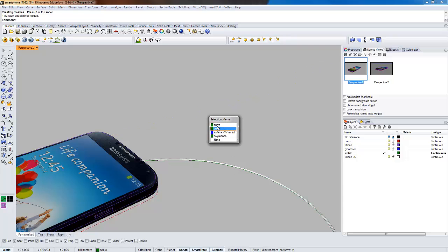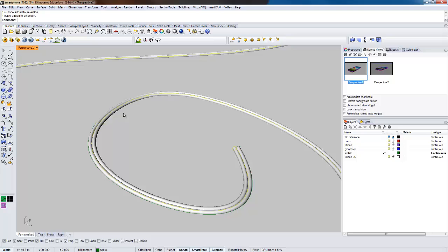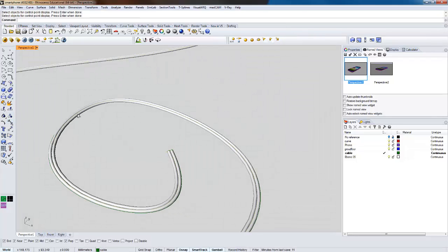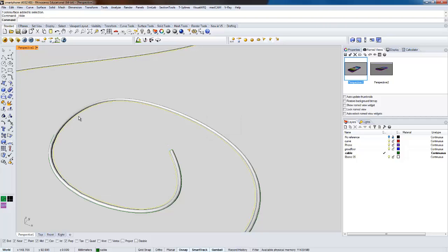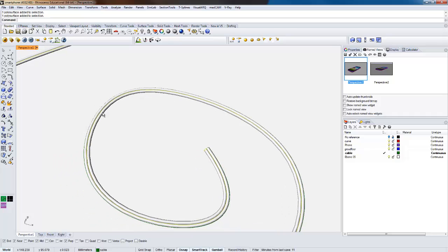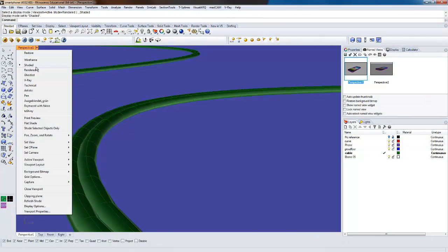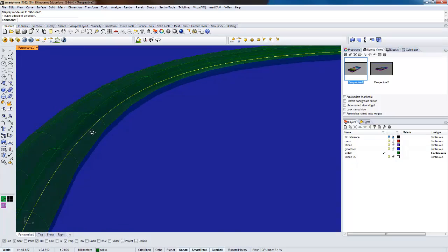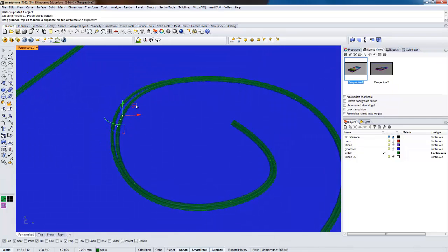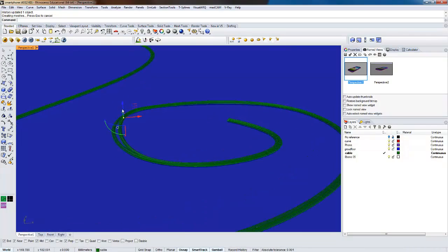And to show you what I meant before, when we change the control points of the curve, let's do it here. Points on. If you have problems getting the curve, maybe go to a ghosted viewport. You can actually see the curve better. Okay, points on. Where are they? There they are. So now you can see you can change the curve afterwards. That's pretty nice actually, and it keeps it parametric, so you could move it up or something like this.